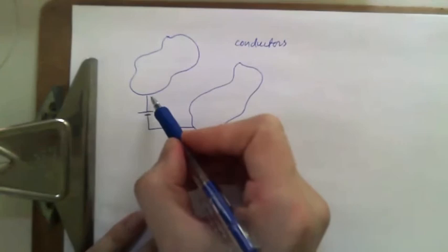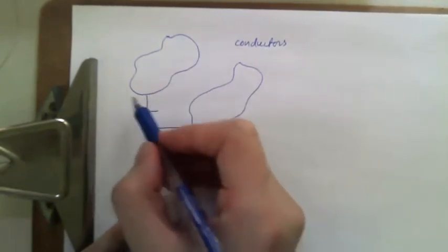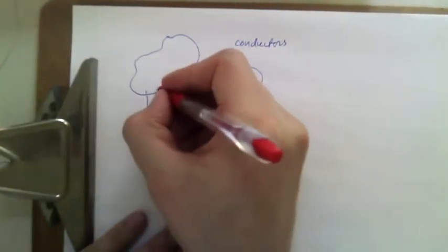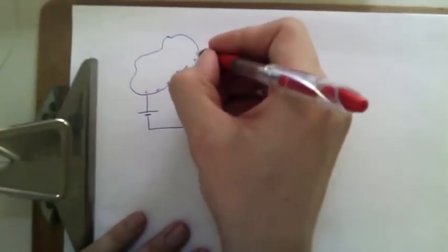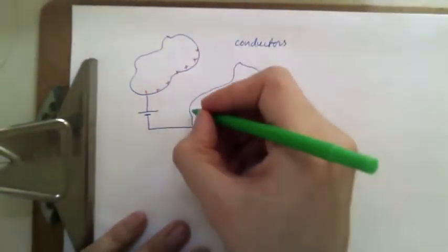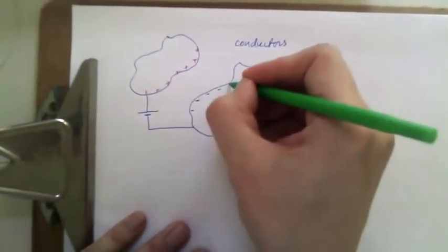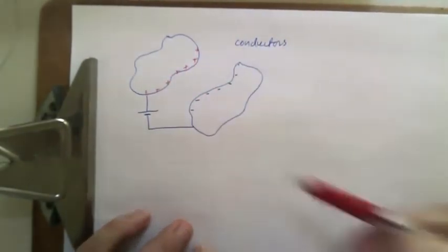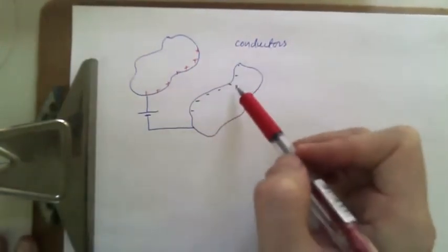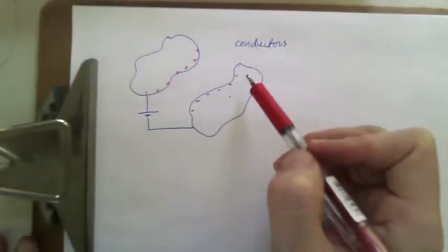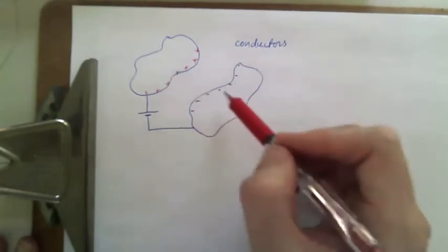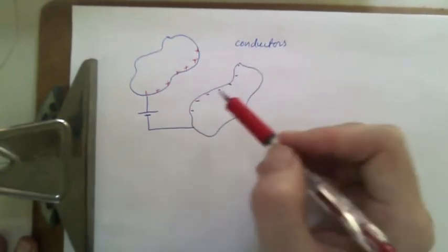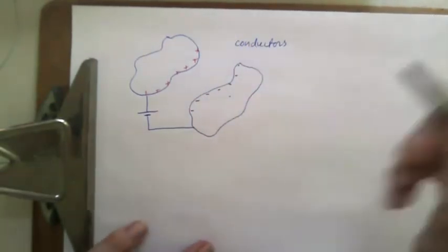So that means that this one's going to become positively charged. Now in this case, the positive charges are again going to try to get close to the negative charges, so they spend most of their time between this gap. And any assembly that you can describe as two conductors insulated by some kind of a gap, you can call a capacitor. So that's the most fundamental building block.